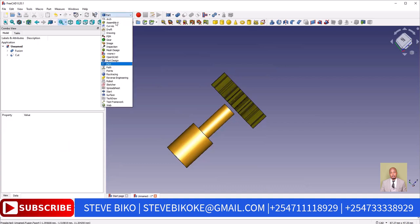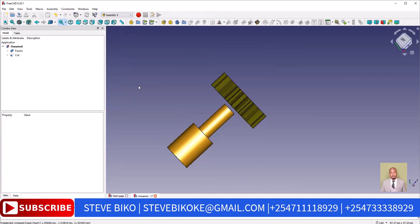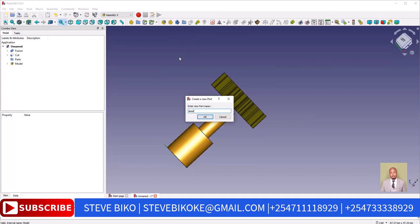Now we go to Assembly 4 Workbench. So we make a new Assembly 4 Workbench model. Then we make 2 parts by clicking on the new part command. We call it axle. Another part, we will call it gear wheel.